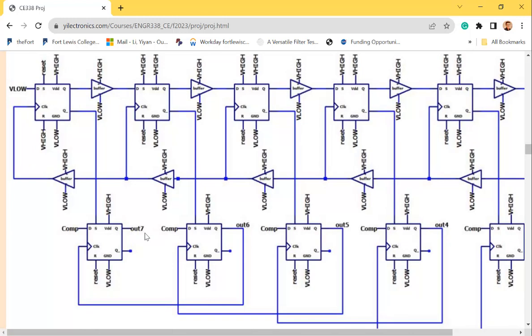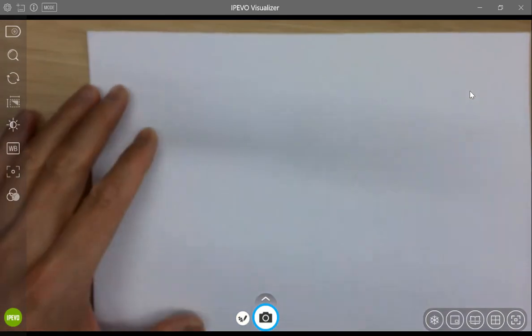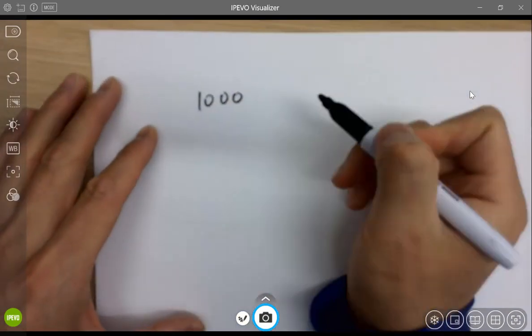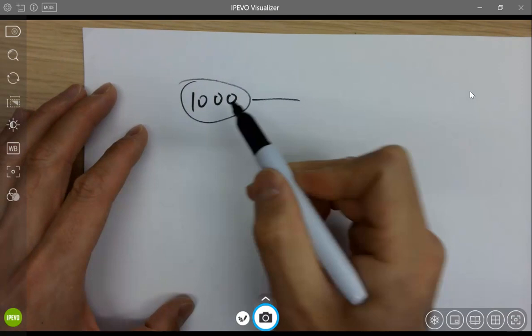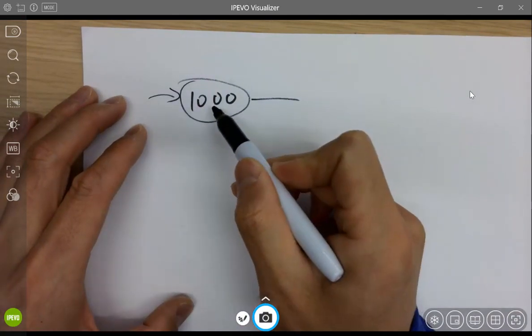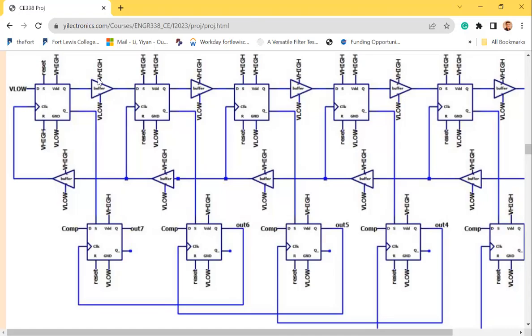So if you try to recall the process of the start logic, you start with what? The very first state is what? Can you still remember that? Remember how we do the start logic, all the conversion? Yeah, one all zeros, right? So the first cycle you have one, if it's a four-bit converter, then it's going to be 1 zeros and then start the conversion. So you need a reset cycle to reach this kind of state for the logic register over there, right? So that's what the reset is doing. You need that one to start the conversion of that cycle.